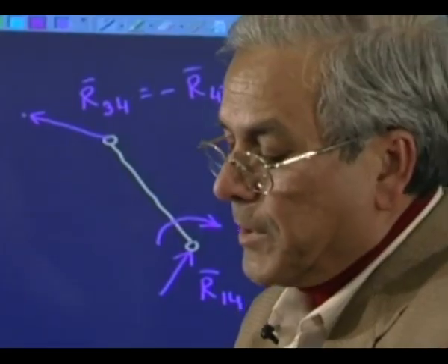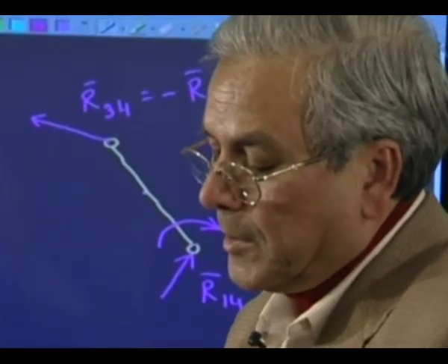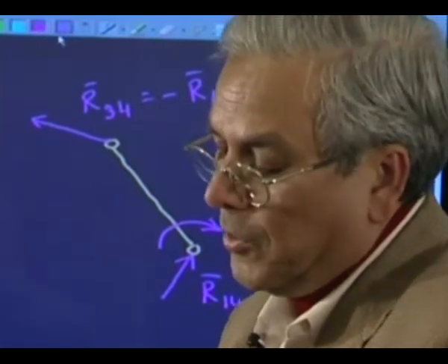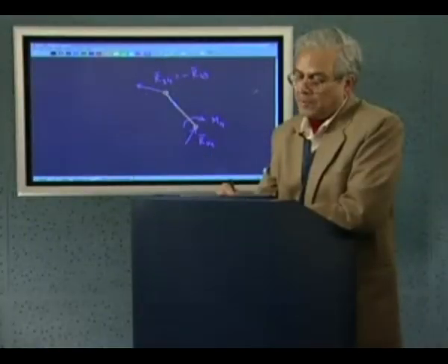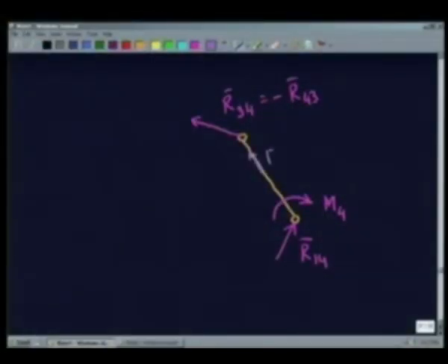Since there is no angular acceleration, the center of mass will have some inertia force, which will be in this direction, because it will be pure centripetal acceleration. So inertia force on link 4 will be purely radial force.